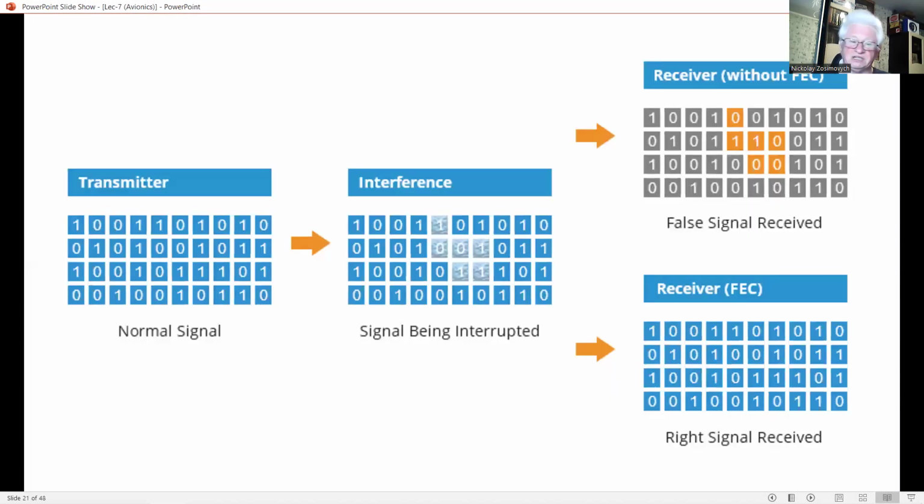The use of digital data transmission enables error check and coding to be incorporated in the digital data word format so that any corruption of the digital data by EMI can be detected and the data ignored. However, the data are lost and the system frozen for the period of the interference, so only a short transient loss would be tolerated.